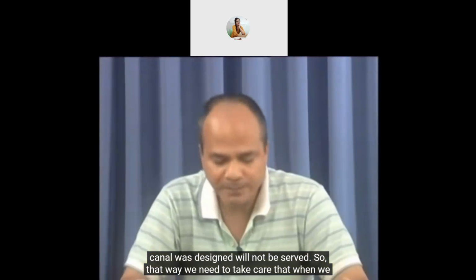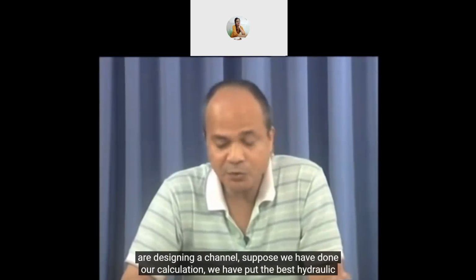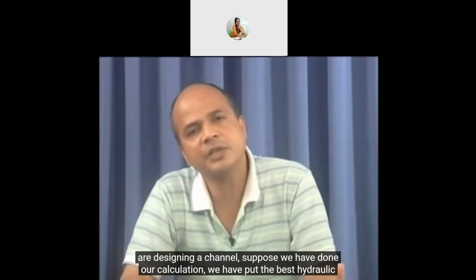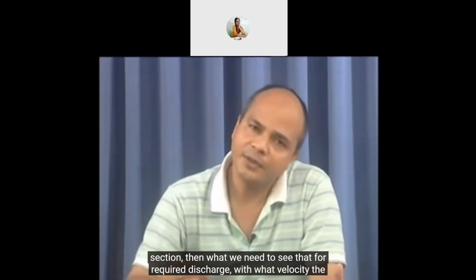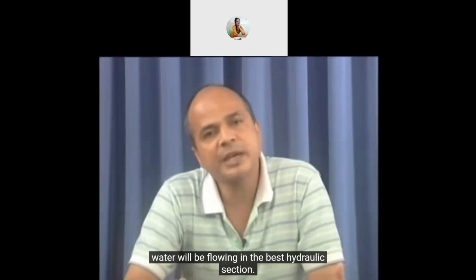So that way, we need to take care when we are designing a channel. Suppose we have done our calculation and put in the best hydraulic section. Then what we need to see is, for the required discharge, with what velocity the water will be flowing in the best hydraulic section.